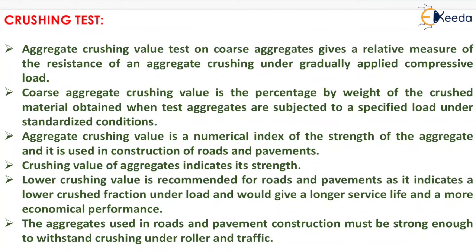Aggregate crushing value test on coarse aggregate gives a relative measure of the resistance of an aggregate to crushing under gradually applied compressive load. Coarse aggregate crushing value is the percentage by weight of the crushed material obtained when test aggregates are subjected to a specified load under standardized condition.